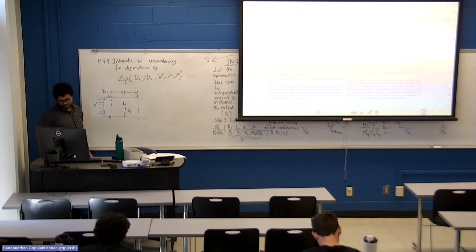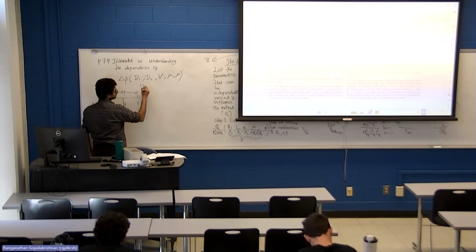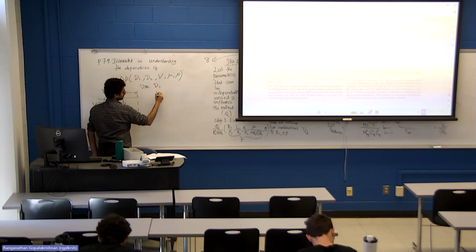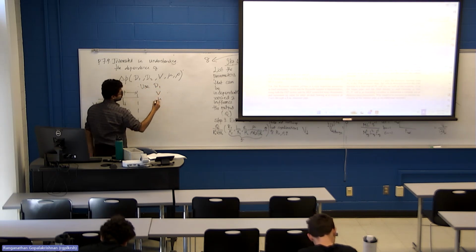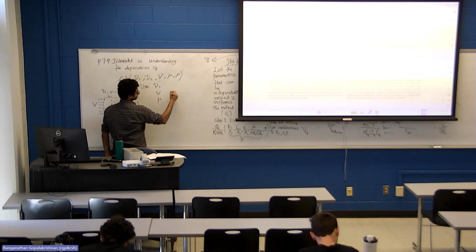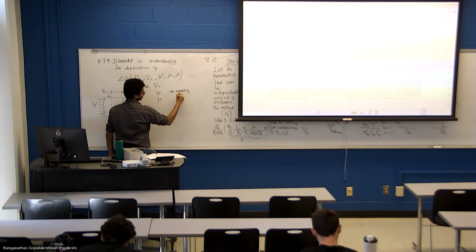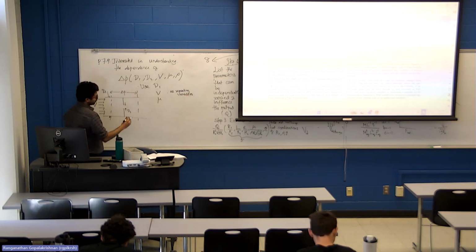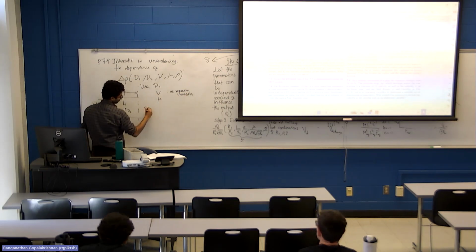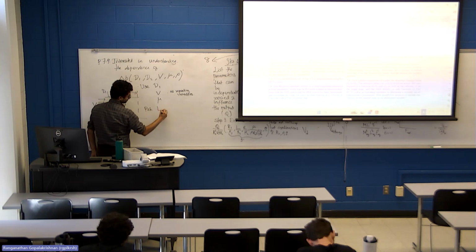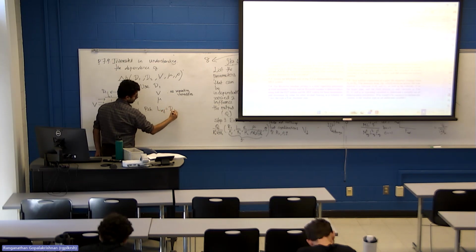So the problem says use D1, V, and mu as repeating variables. I'll tell you what that means. What I told you is pick a reference length, which we'll pick as D1.